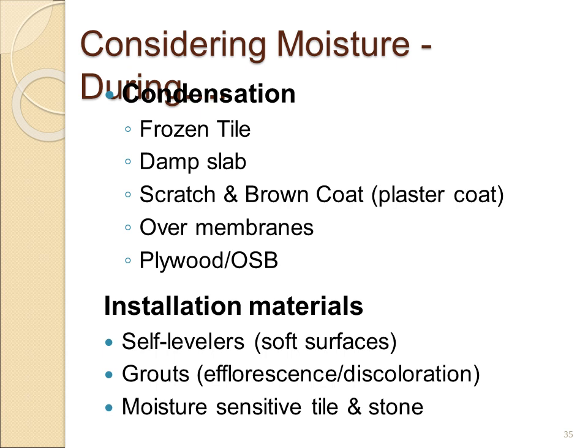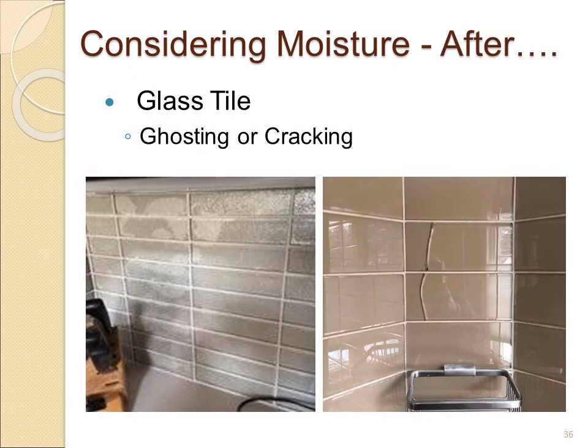So now you have an impervious membrane with a substantial amount of mortar and moisture, and that moisture could go into your stone and you won't see the effects. It could be up to 40 days. And then all of a sudden your stone will start to warp. And if you've ever seen it, it's a very strange and eerie thing to see stone actually deform like that. But definitely it can happen through moisture.